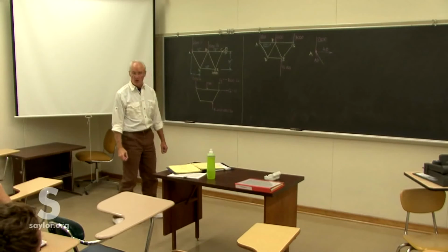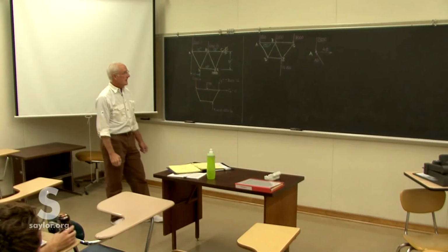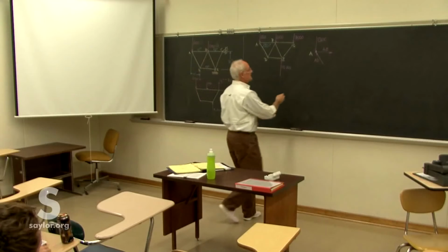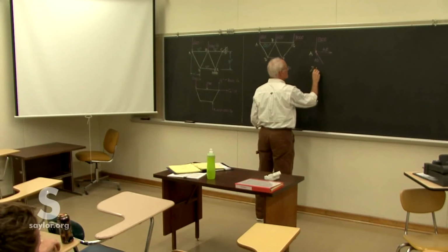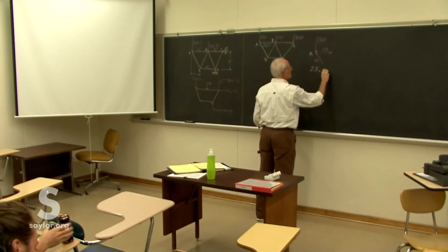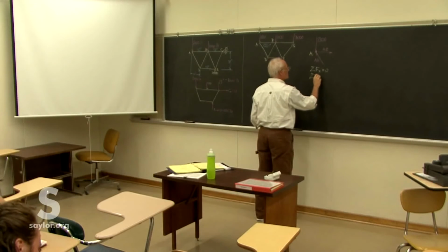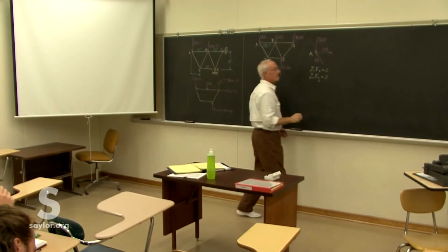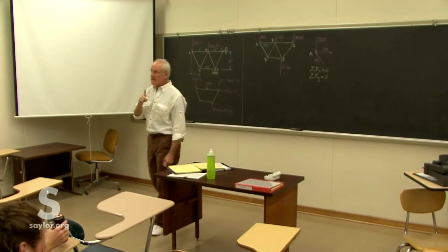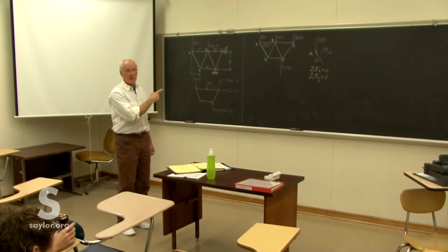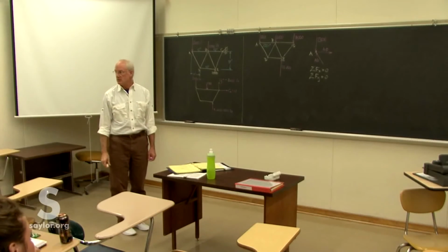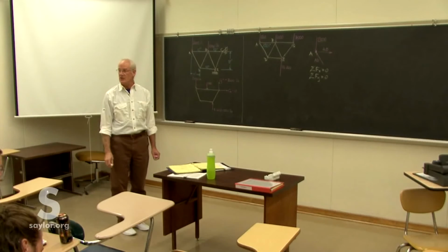And so now I can solve for those by simply summing the forces in the X direction, summing the forces in the Y direction. We're lucky. We have two unknowns, there's two equations, we should be able to solve the problem, at least solve that joint.